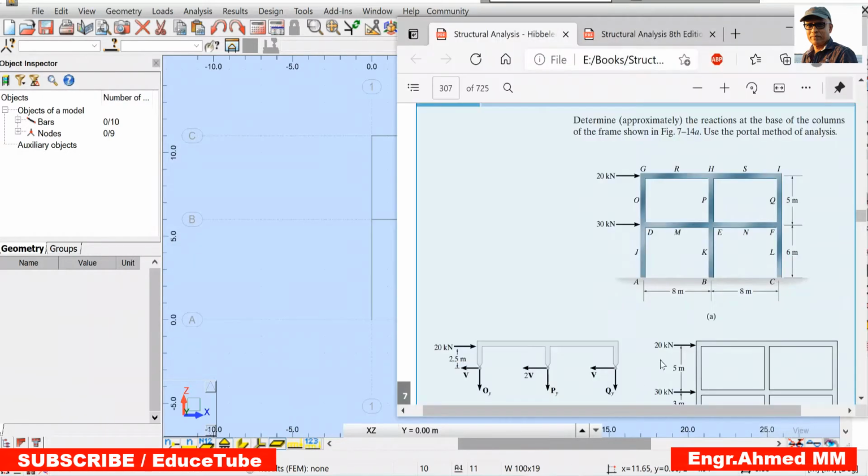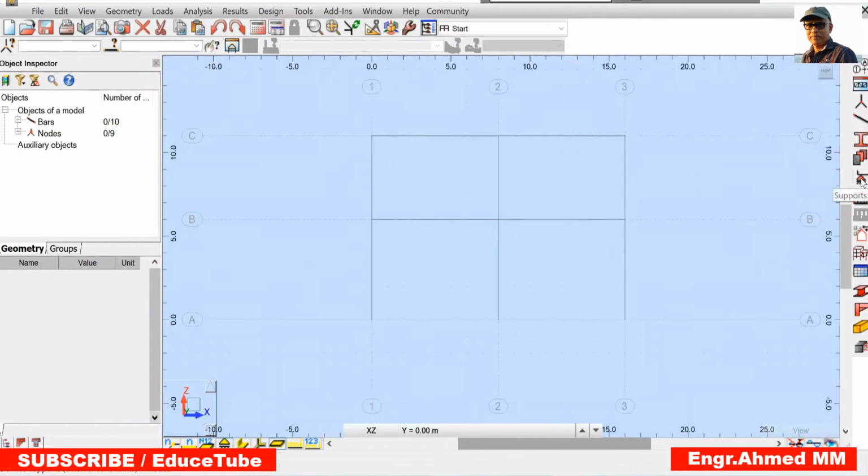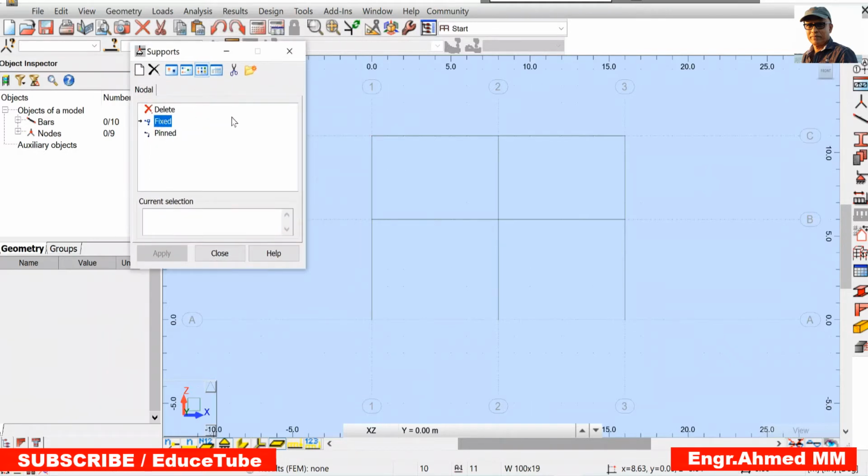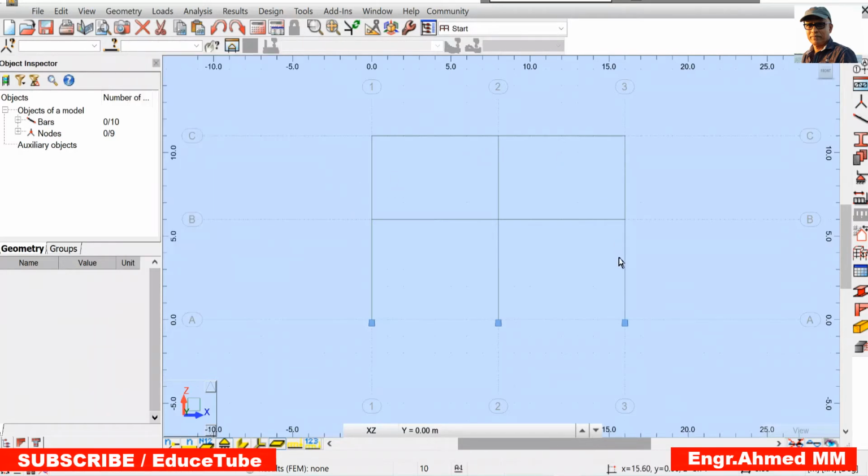Now we have to provide the supports. So let's see. Click on support. Take fixed support here and here and here. So supports are done. Close it.